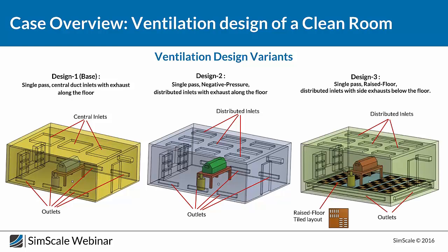And our third design is a little more advanced. We call it raised floor. As you see, the floor is slightly raised. It's tiled with a certain type of tiles. You can see we've shown one of them here that has certain patterns inside it to let the air flow through it. These are completely covering the raised floor, so the air is allowed to go through them, and then we have large outlets under the floor to actually let the air out. So this is the third design.